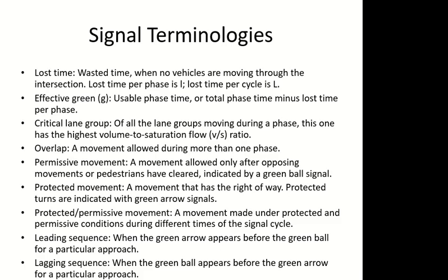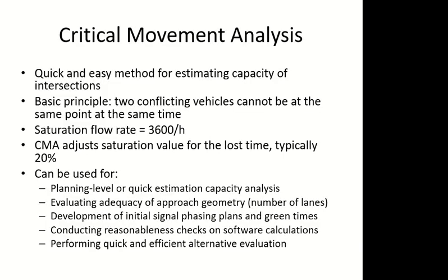Okay, sometimes you have overlapping phases. The movements can be permissive, protected, or they could be a combination. If you are allowing left turning first and then the straight, it's called leading. If it is the other way around, it's called lagging.